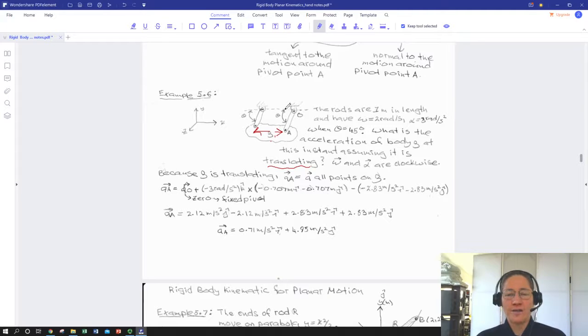Both of these bars are rotating versus this fixed pivot, but this rigid body isn't, because these 2 points have to stay effectively along the same line versus our external reference frame X. We can say that our rigid body is translating. I'll just put a little I hat here versus our external reference frame. We'll call this F. So like the frame of the ceiling here is our external reference frame. Okay, what was wanted? What is the acceleration of body B?